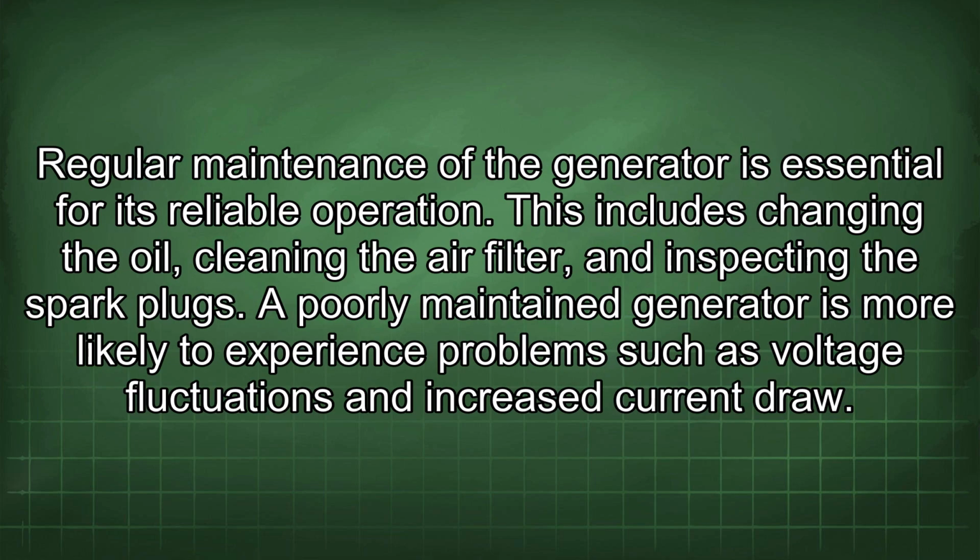Regular maintenance of the generator is essential for its reliable operation. This includes changing the oil, cleaning the air filter, and inspecting the spark plugs. A poorly maintained generator is more likely to experience problems such as voltage fluctuations and increased current draw.